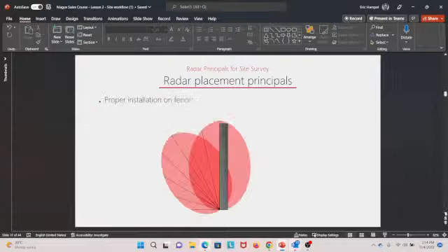In general, we tend to say, instead of pointing the radar all down the fence, let's point it towards the area of interest. Let's say the focus is on the internal, and here's the internal side, here's the external side, divided by the perimeter line, by a fence. Then point the radar, first of all, a little bit to the inside, with some 10 degrees as an example, and therefore optimize the coverage on the inside. That gives us the chance, as we can see in comparison, to have pre-alarm quite significantly.